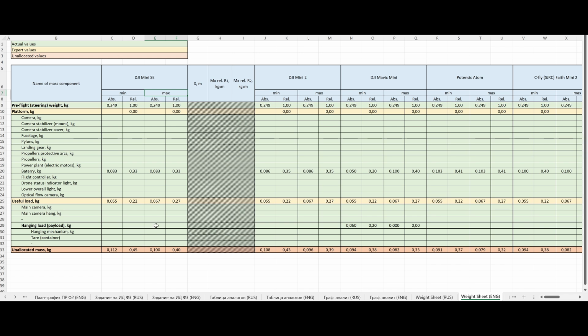The logic of the transition from yellow to green is simple and is embodied in the principle of forming a weight list, according to which the actual value in the formation of a weight sheet prevails over the value obtained using statistical weight formulas. In particular, as soon as at least one actual mass value appears in the useful load section, we immediately proceed to work with the actual values to transform the conditional delta to the undistributed weight section of the weight list.